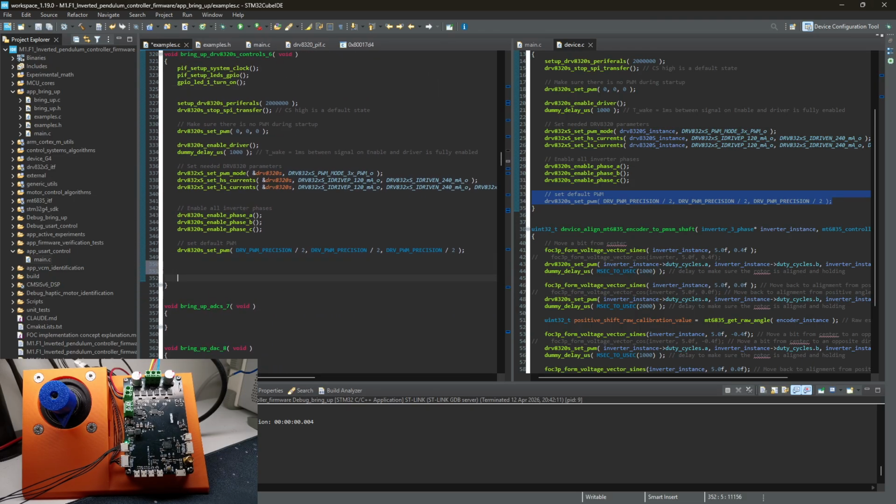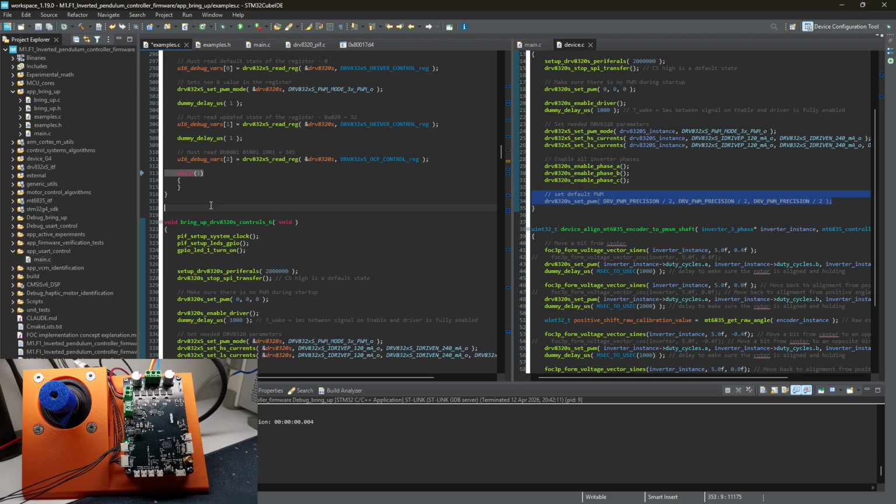And at this point, we need to do something to rotate the motor. They have a feature to rotate the motor in open loop, so it's very easy. We don't need any feedback, any sensors, anything at all. So it's actually more of a PWM test and PWM implementation rather than the IC test.